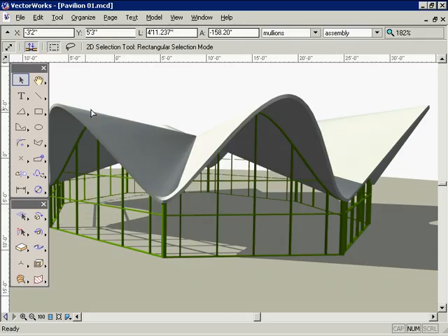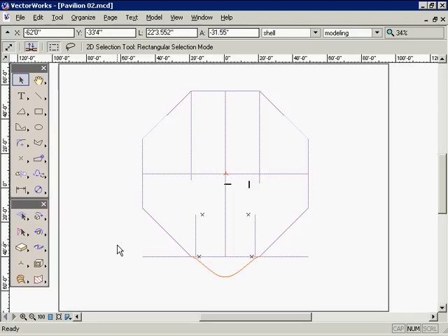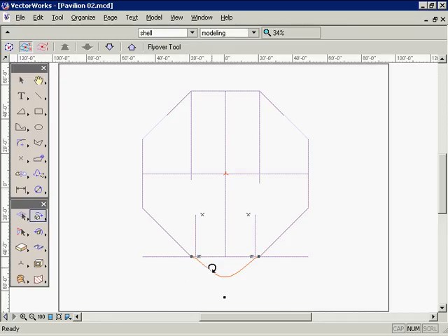It has a roof that is an undulating parabolic curve, and glazing that encloses its sides. Note how the mullions and glazing fit up against the curving roof. To begin, I've laid out some 2D guidelines that will give me snap points as I model the different components. I've also created a NURBS curve that defines one side of the roof perimeter.